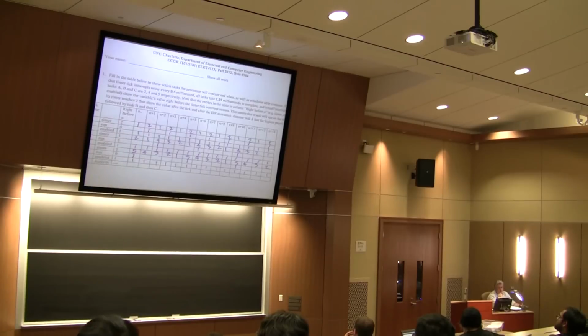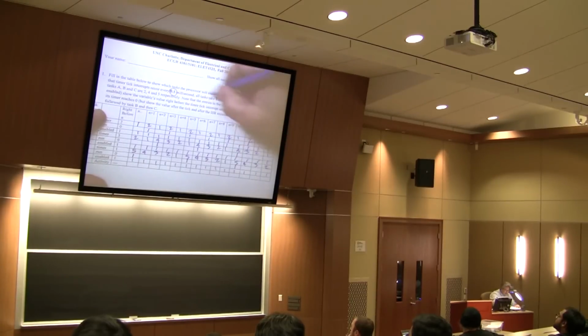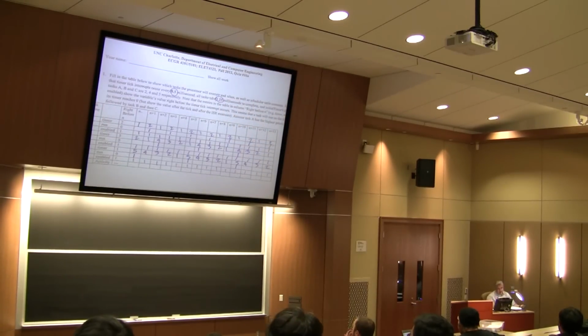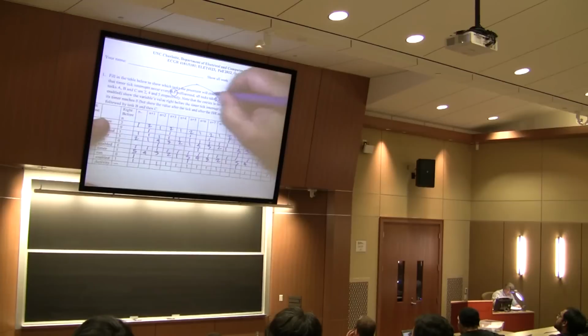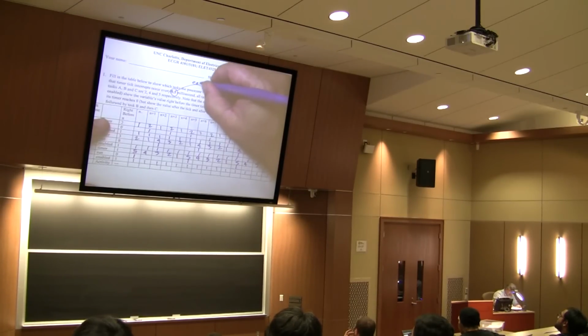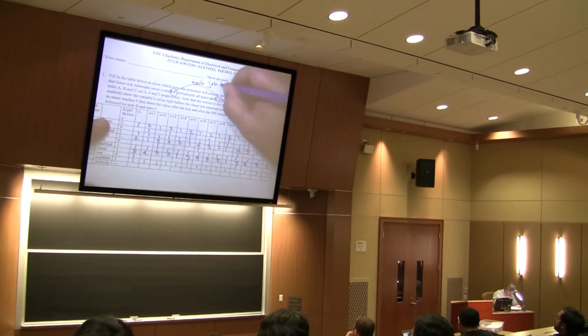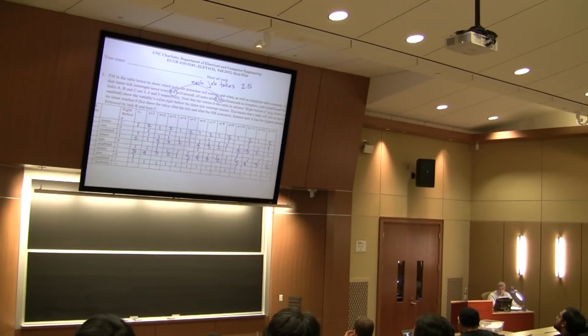So what I've done so far is I've shown what will be computed in the interrupt service routine that occurs every time you get a timer tick. The funny thing is, it really doesn't matter how much real time it takes. What does matter is that each job takes how many timer ticks? 2.5 timer ticks worth of time. So, let's look at how often things are going to be going on.